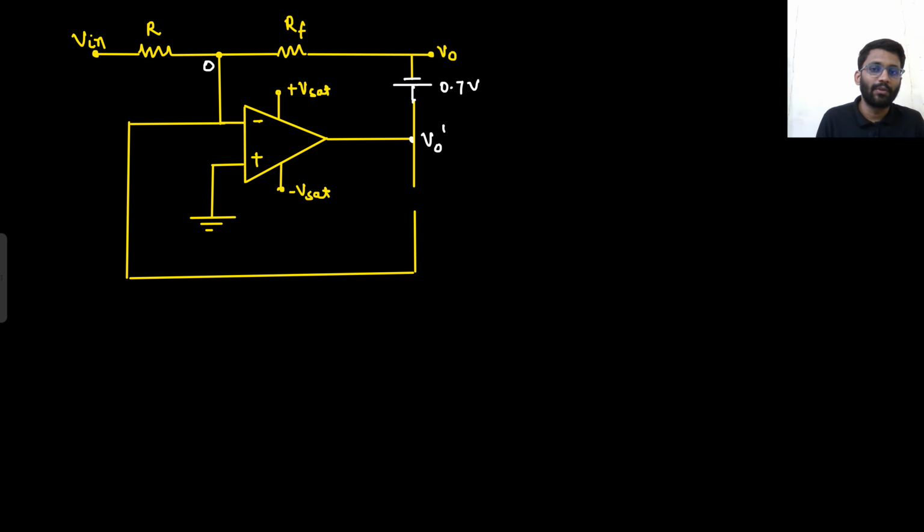No. Because RF is coming into this loop. The output of the OpAmp can drive some current. I0 current. This current can flow from here. This current can flow from RF. So the output of the OpAmp can drive some current. So certainly this RF is not driving 0 ampere current this time.